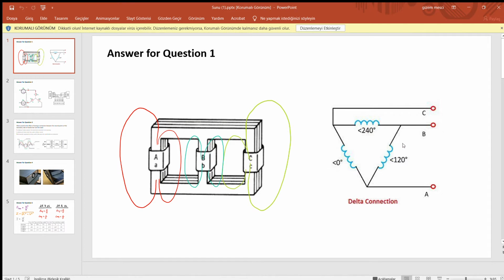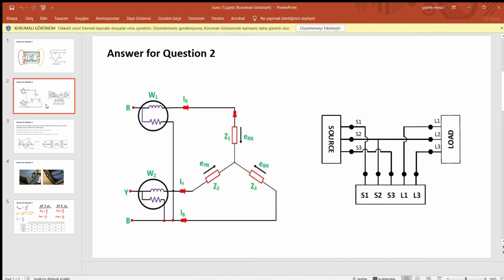Another reason may be the third harmonic component of the current. In fact, the phase magnetizing currents in a transformer should contain third harmonics in order to produce a sinusoidal flux. Delta connection of three-phase systems only allows the sinusoidal flux and voltage with no third harmonic current in the transmission line. However, the third harmonic components can flow within the phases. In other words, the third harmonics create a circulating current around the closed loop of the delta connection. Therefore, in delta configuration of three-phase systems, the phase currents may differ due to the third harmonic circulating current.